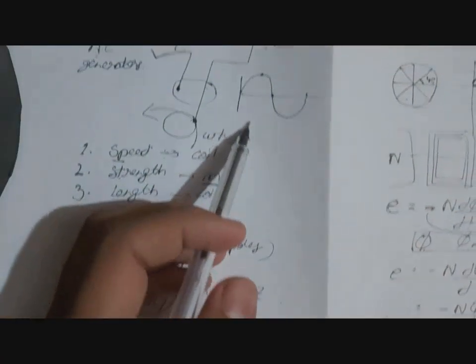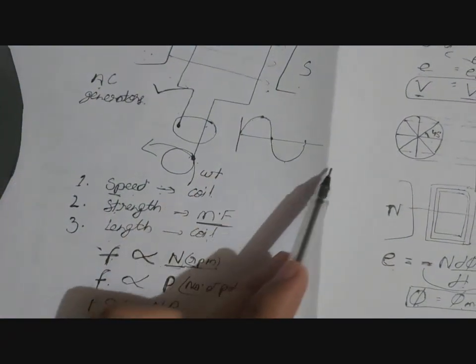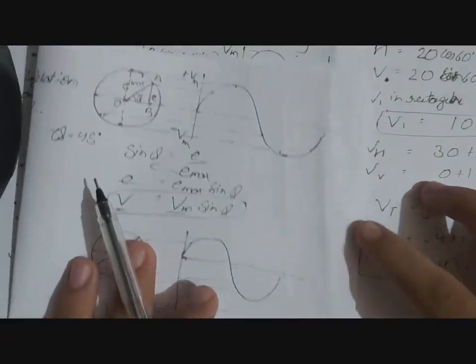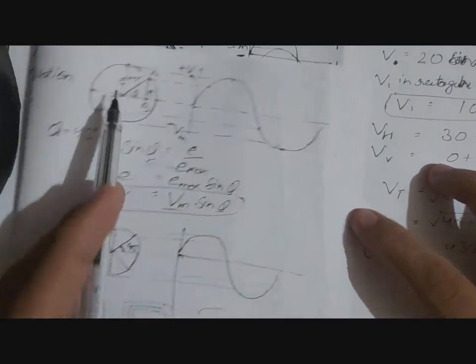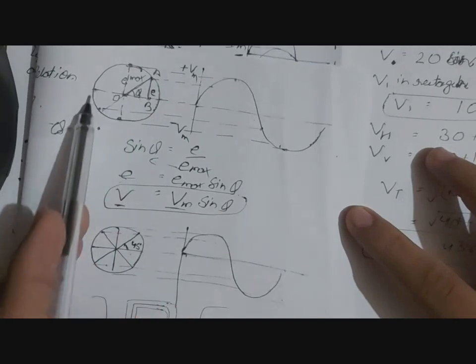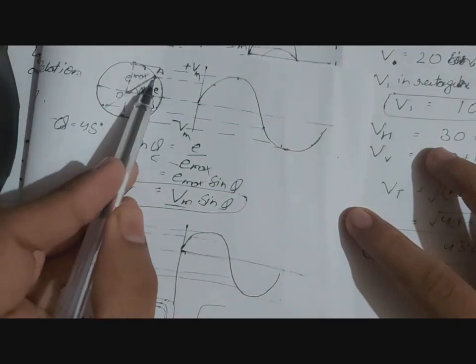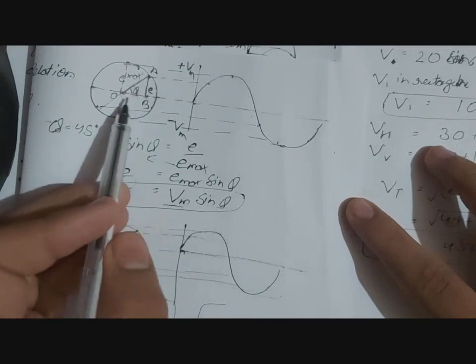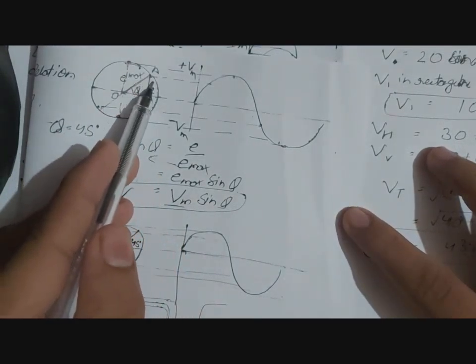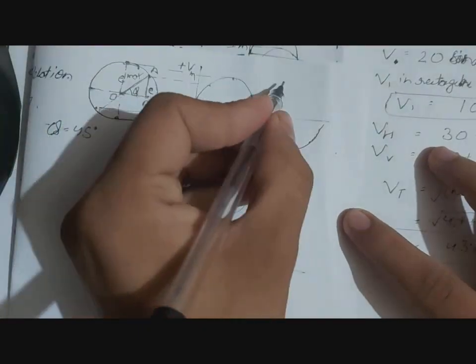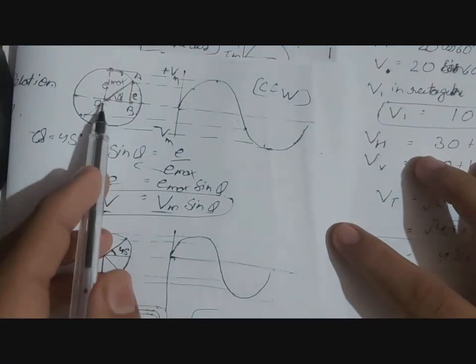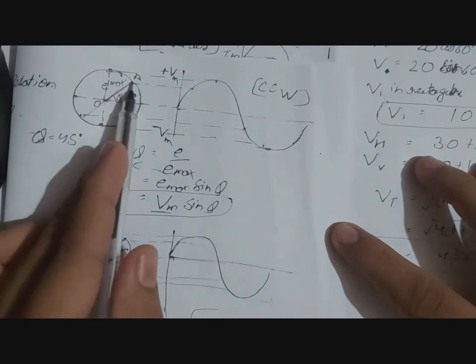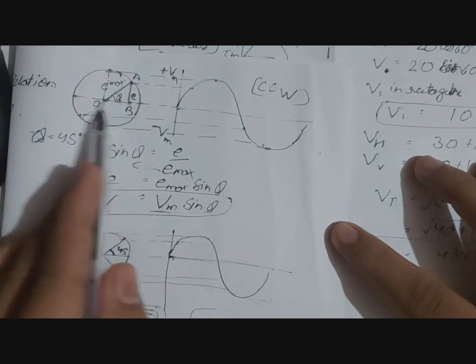Secondly, the formation of this sinusoidal can be understood with the help of phasors. Let's take an example. We will discuss it in detail, but here is only an example. This is a phasor and OA shows the maximum magnitude. When this moves in the counterclockwise direction, CCW, the projection of OA on the baseline shows the magnitude.